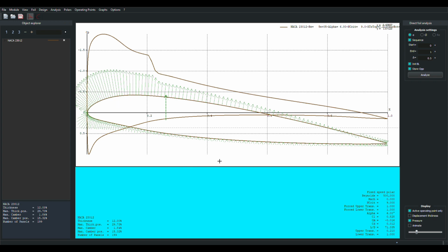And out of the NACA databases, this is one of the most efficient airfoils that you'll find in there in terms of L over D. It's not the best, but it is one heck of a good compromise. And even if you're doing a conventional configuration, this allows you to keep the smallest horizontal tail possible because you're not having to counteract a lot of nose down pitching moment. Okay, so that said about the 23012, this is the airfoil I use out at the tip of my wing.